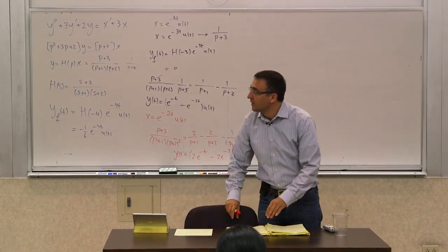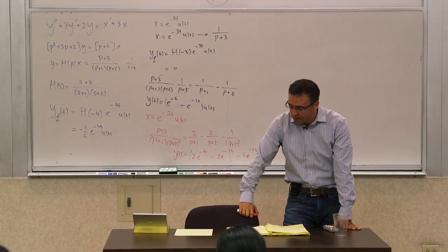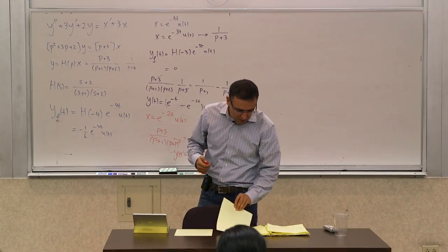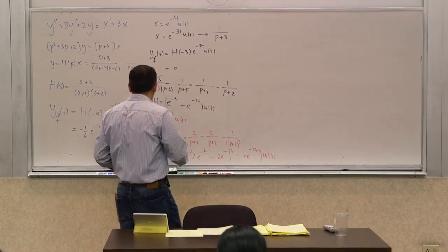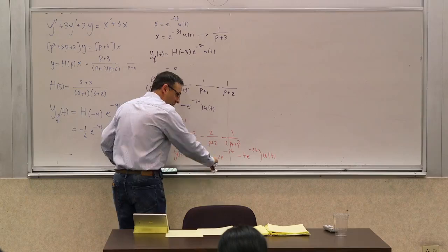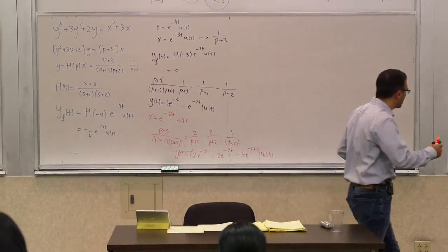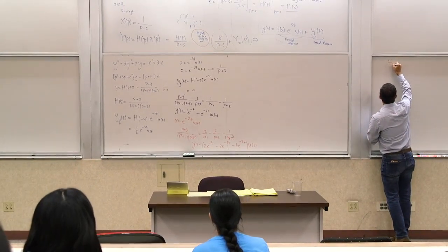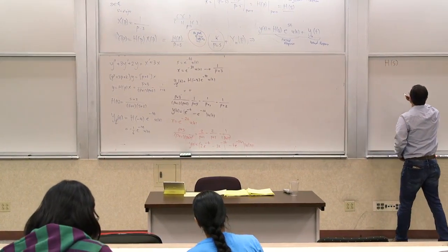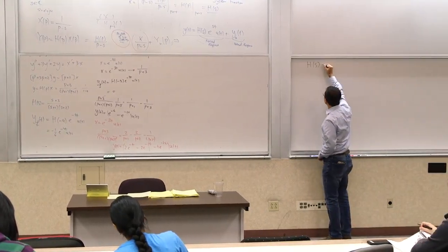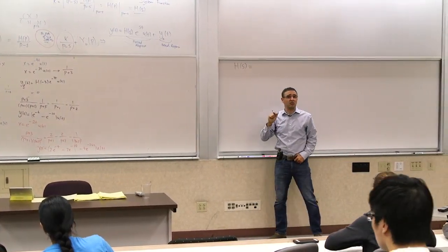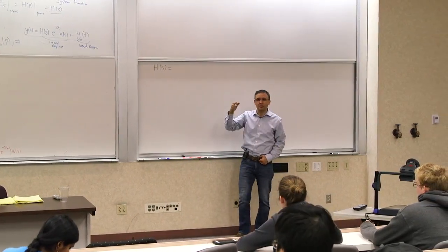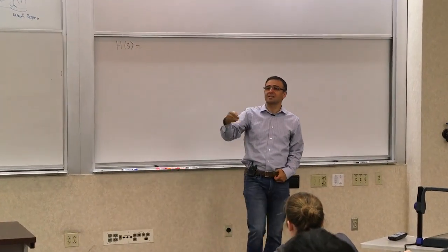All right, any questions? Okay. So this development brings us to the next thing we want to talk about, a related thing, which is the concepts of poles and zeros. As we discussed, these are the roots of the numerator and the roots of the denominator of a system. So let's say you have a system function, or transfer function. If it's a rational system function, and in the most general case, systems are not necessarily rational. But for lumped systems, they are.